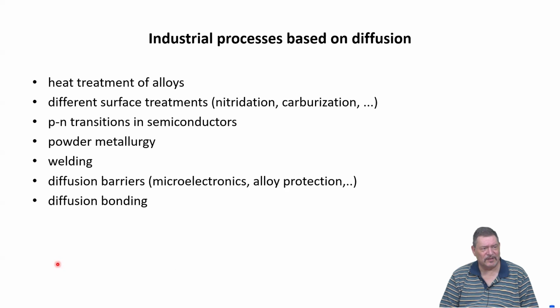And unfortunately, it's used by industry to calculate how long your smartphone will work. You know, because this is engineered to fail, because the diffusion processes will occur at the operation temperatures, and after a certain amount of time operating at this temperature, industry can exactly calculate: okay, now the diffusion process was so severe that sufficiently high numbers of transition metals have entered the semiconductors, created new states in the band gap, which means the system fails.